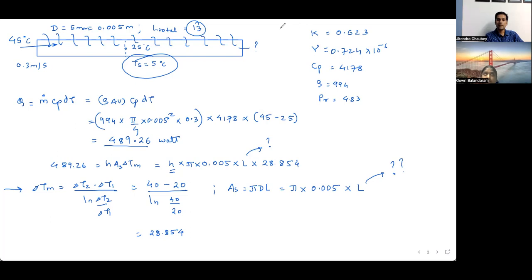That is only possible in a counterflow arrangement, where two fluids flow from opposite directions and delta T is always constant. That is only true when delta T at entry and delta T at exit are the same, which is clearly not the case here.